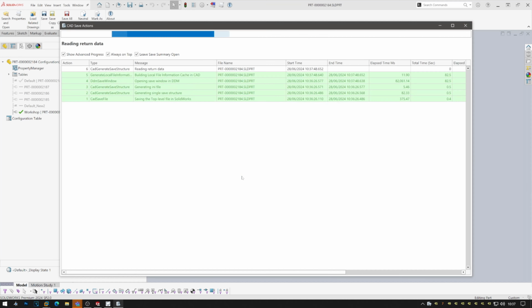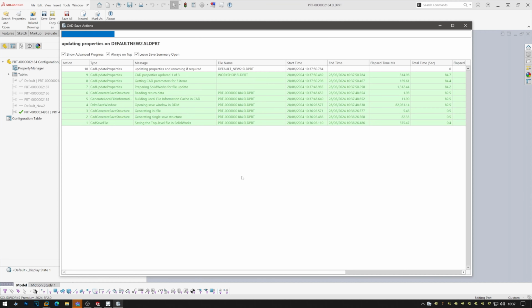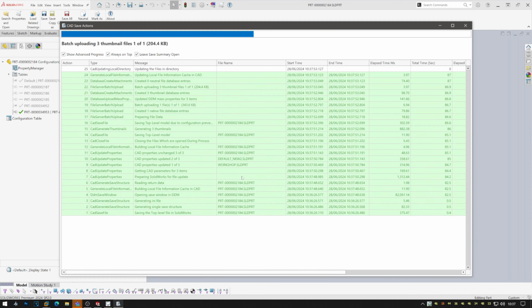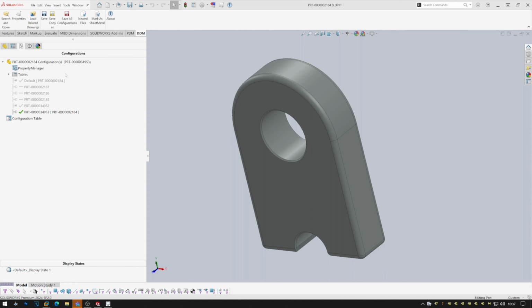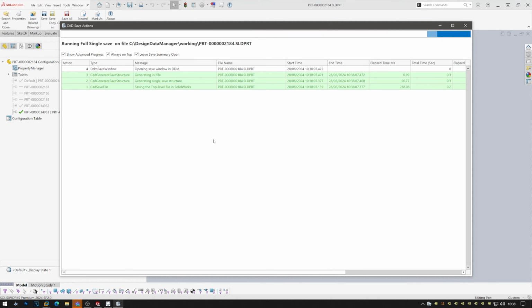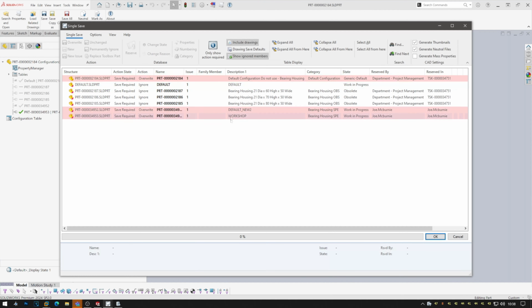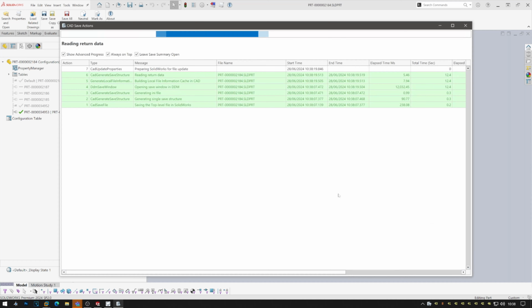And there we go. So much more visual in terms of handling both assembly and part configurations, and considerably quicker as well. So I've added my new configuration to this particular family. Again, if I do save all configurations, it will only let me overwrite the ones that are modifiable. If they are released, I can tell it to permanently ignore them, as I've done with these obsolete ones. And I say OK, and it will go and do that for me.